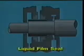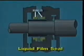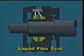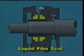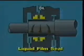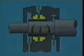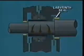On high pressure and heavy-duty compressors, liquid film seals are the most common. A typical seal consists of 2 or more rings that don't rotate but are free to float with shaft movement. Oil is injected between the rings at a pressure higher than the compressor suction pressure. This allows the oil to flow between the seal rings and the shaft and then into the oil drains. Labyrinth seals guard against any oil leakage into the gas stream.